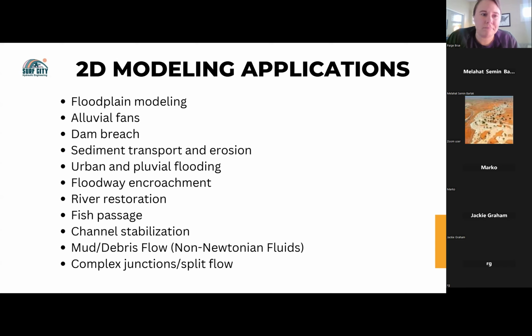For example, if we need a big culverts, if the water is concentrated in one place or spread, as we are working in deserts area for most of the time. And for the dam resolution, we used only this purchased one of 5-meter resolution. I don't think it is giving accurate results. Sometimes it varies. HEC-RAS, for example, is giving 600 cubic meter, and rain on grade is just 1 or 2 cubic meters. So it's a big difference between the two.